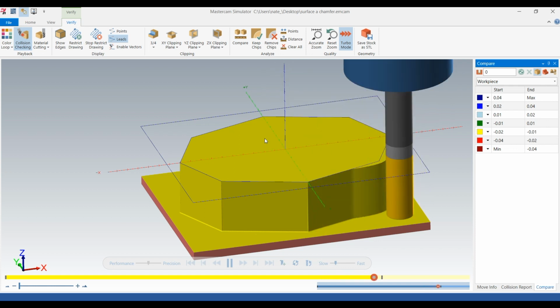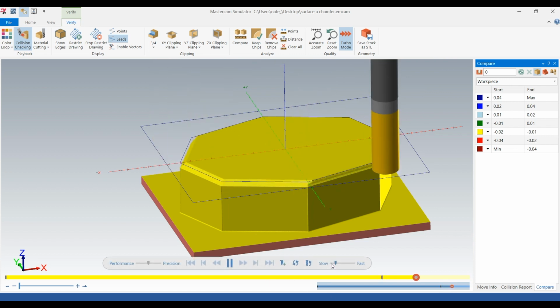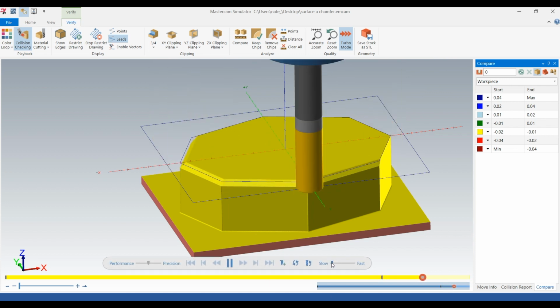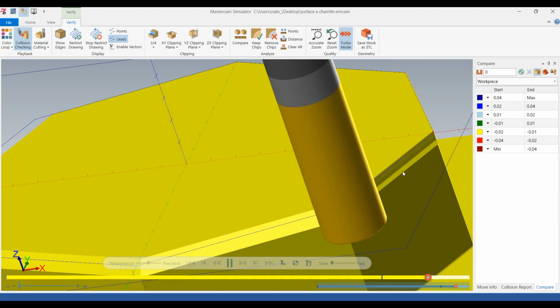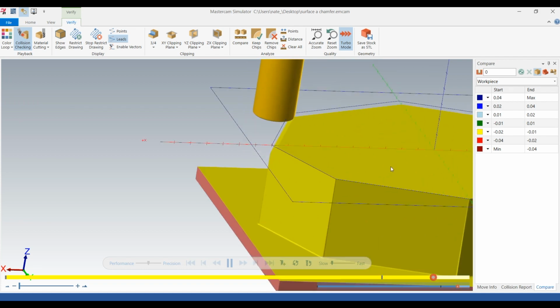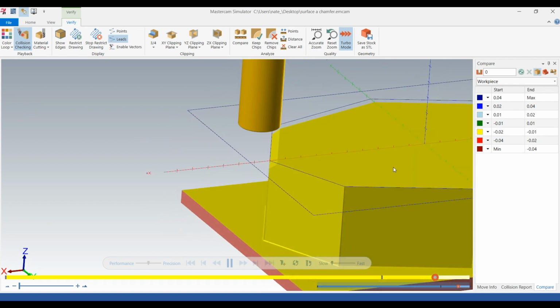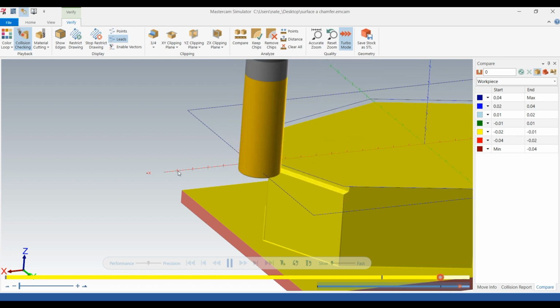Next is the flow line. So it's zigzagging up. We're going to slow it way down. So we changed our distance to 3 thou, right? So every time it goes across that surface, it's going 3 thou further than the last pass. So it's like 3 thou between x, y, and z.